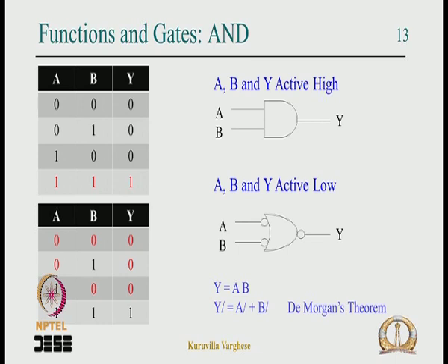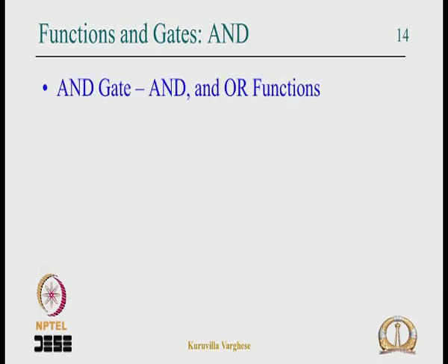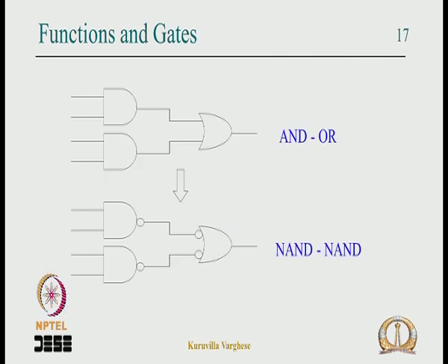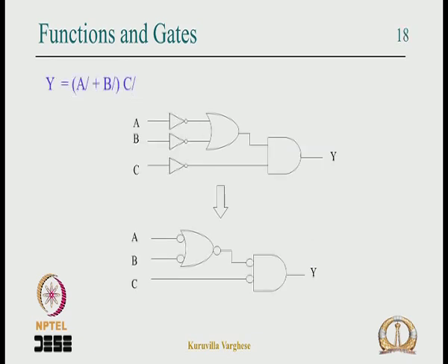Then it is bringing De Morgan's theorem into our concept, and we have seen that NAND and NOR are universal gates, and we have seen some examples of AND OR getting implemented using NAND gates, and also how advantageous it is to conceptually think like that. Then you will not waste gates if you bring this into concept while designing simple logic circuits.